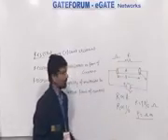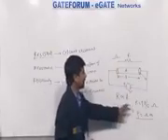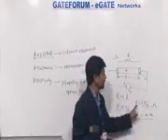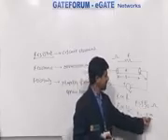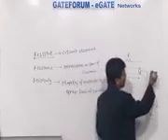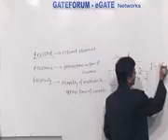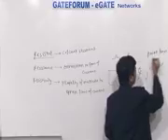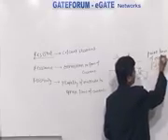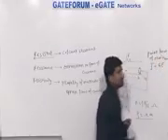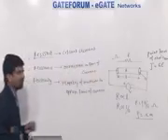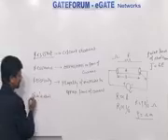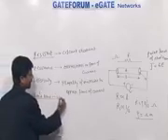So basically this is the basic definition, that the resistance of a material is directly proportional to length of the material and inversely proportional to area of cross section, and rho is nothing but resistivity, which is given in ohm meter. In the form of field theory, I can say that J equal to sigma E is the point form of Ohm's law. But let us try to understand what is basically Ohm's law. So we can say that it is applicable to linear elements.